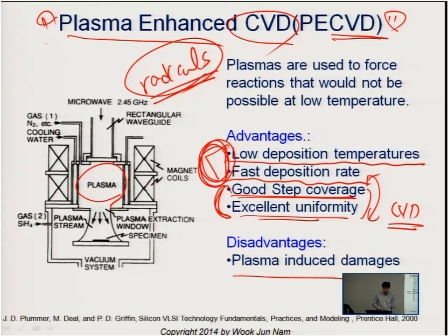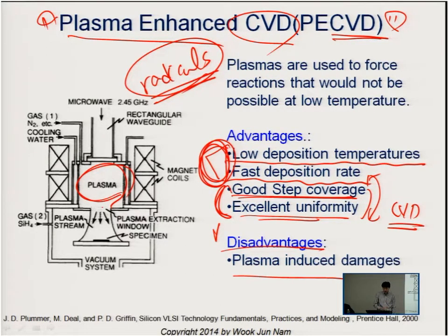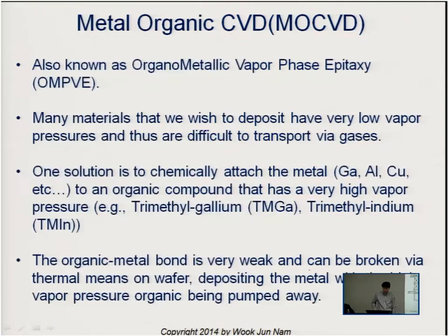But the disadvantage is that since we are using plasma, we can cause some plasma induced damage, and the film quality is much poorer if we directly compare it with film deposited by LPCVD.